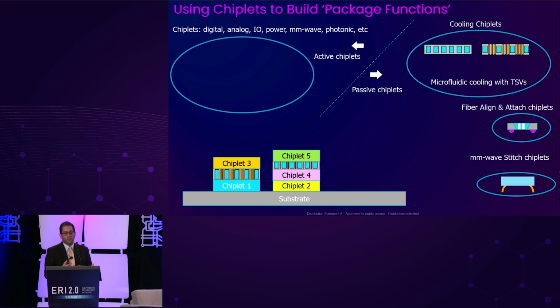And more recently, we've demonstrated millimeter wave chiplets where the sole function is to provide low-loss, seamless connectivity across an array of millimeter wave chiplets, irrespective of their heights, pad density, and pad materials.